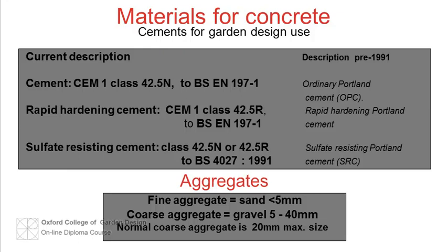The quality control of ready-mix concrete is excellent if it is supplied under the quality scheme for ready-mix concrete. The control over hand-mixed concrete is least satisfactory. Poorly batched and mixed concrete may not be durable. Durability may be vital in conditions of severe exposure, like a domestic drive, and the surface could crumble within a year or so if it is not durable.